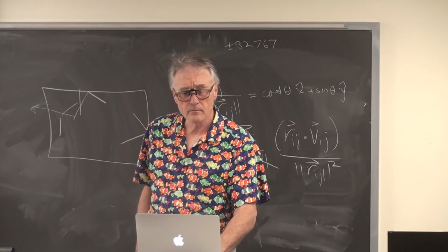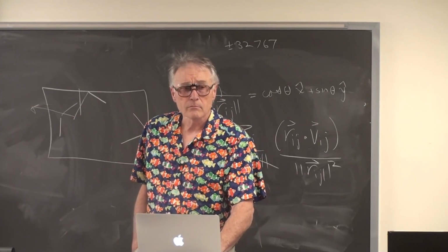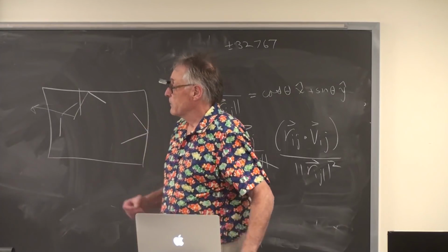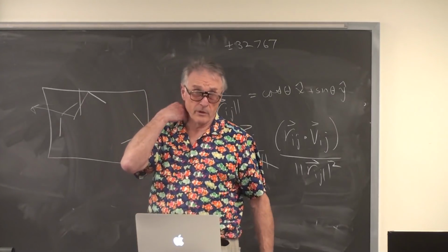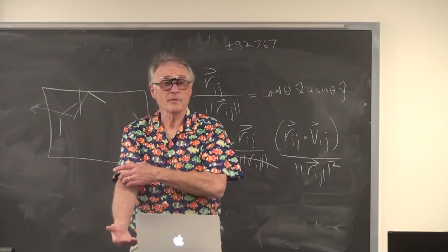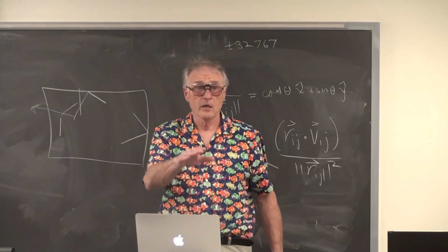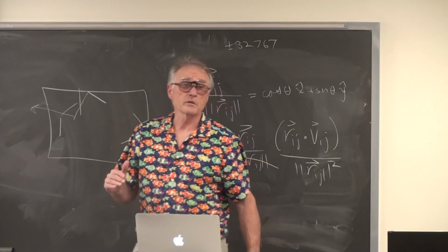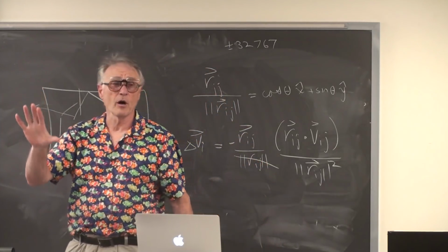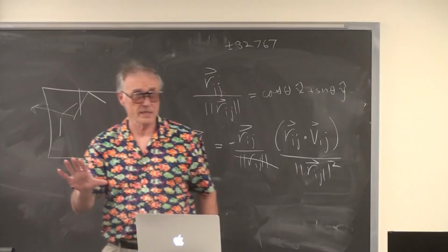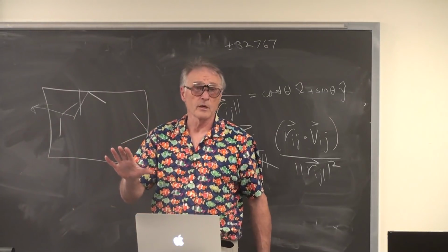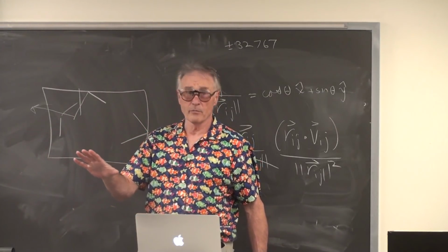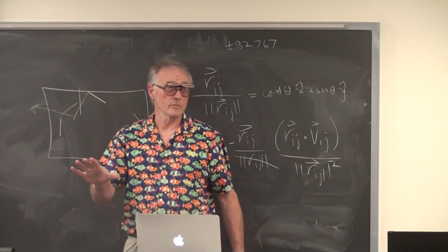So you said, when you say run out of time, is that the time when there is no yield time in that protothread? And like the protothread would be called again on top of itself? Well, it will never, because it's a non-preemptive system, it'll never actually do that. But instead what will happen is your frame rate will go down. So the system will start to bog down and run slower when you run out of cycles in that compute loop. So efficiency is going to be important.